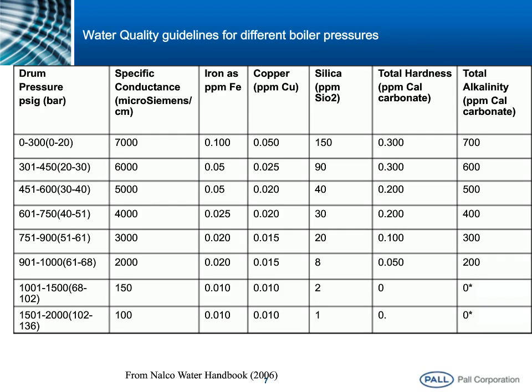What we're tracking typically, the big contaminants, are iron, overwhelmingly iron, but you can also find copper. And then you'll have things that could come in from a variety of sources in terms of silica, even hardness, and we'll also measure alkalinity. As you can see, as you go down this table, the specifications become more and more stringent, but overall we're looking really in the ppb range.